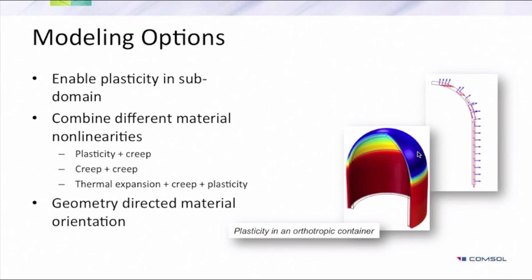If you prescribe plasticity to the rest of your structure, you will end up with zero-value strains. And if you know it already from the beginning, you know that there will be linear behavior there. So there is no need of prescribing plasticity everywhere. So by the decomposition of your structure into subdomains, you can actually save a lot of computational time.